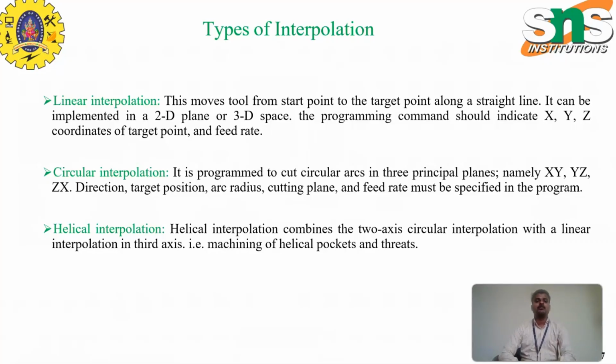The third one is the helical interpolation. Helical interpolation combines circular interpolation in two axes with linear interpolation in the third axis. This is used for making helical pockets and threads. More complex shapes are produced using circular and helical interpolations compared to the other two.